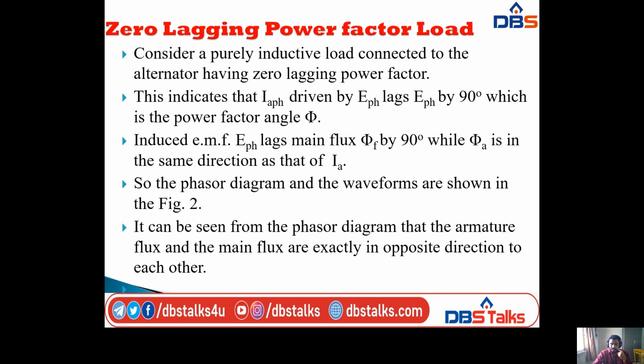And next, coming to the zero lagging power factor load. In this case, I am considering a purely inductive load. In the previous case, for the unity power factor, I took a resistive load. Here I am taking a purely inductive load connected to the alternator, having zero lagging power factor. This indicates that I_A phase, the armature current per phase, lags E phase, the induced EMF per phase, by 90 degrees, which is the power factor angle phi.